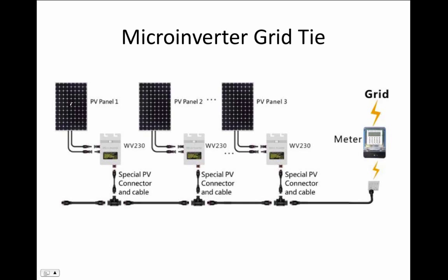And so in this case, the way this works is the solar panel puts out DC. It comes down here to this inverter. This is the plus and minus DC. And then in this inverter, it's converted into utility grade power. And on this side is like a long extension cord from a circuit breaker in your house, or an outlet in your house. And so this is AC from the power company that's actually run to each panel on the roof. And then each panel has its own inverter.